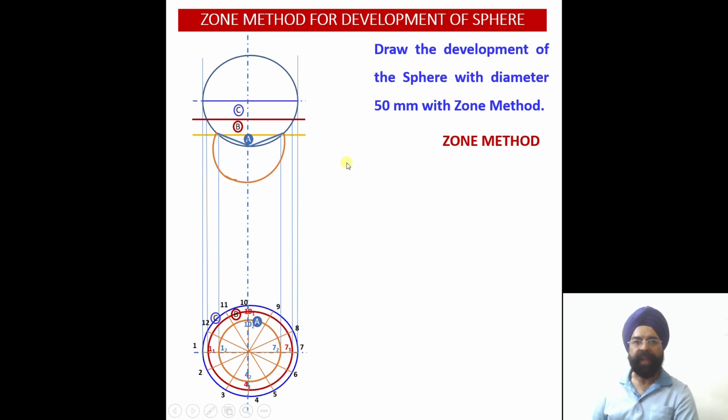So let me do it. I know the sector width over there. Just see, this is my point 1 corresponding to the green circle. Corresponding to the green circle, one sector I need to measure, because all other sectors, they are also equal. Now starting from point 1, I have drawn first arc, I obtain point 2. I have drawn second arc, I have obtained point 3. So this way, one by one, 4, 5, 6, 7, 8, 9, 10, 11, 12 and then again 1. 1 will lie here. So I started from 1, I have ended at 1.